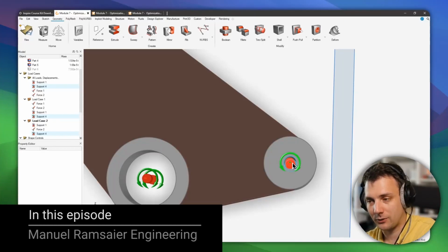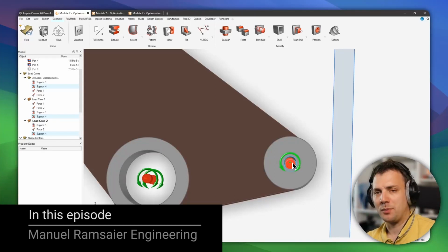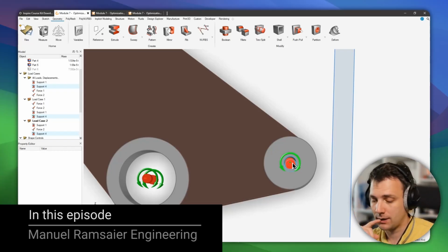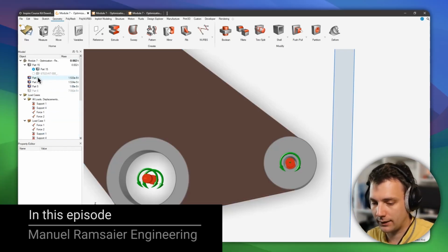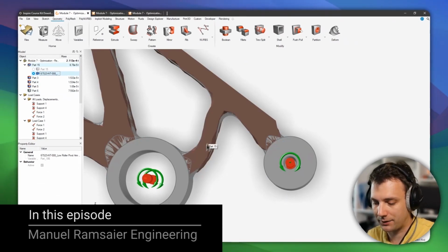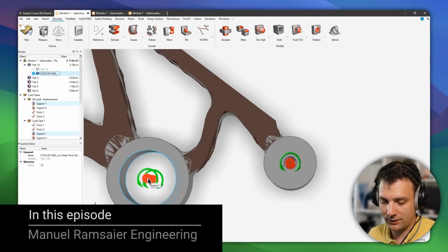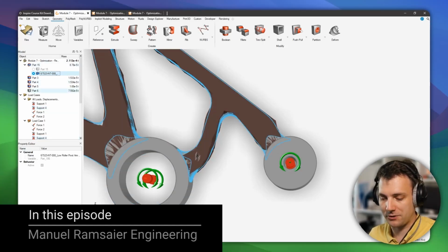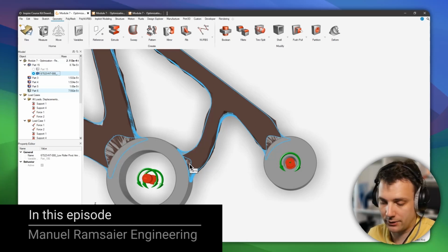But the point I'm trying to make is those two bearings right now, as they are set up, have infinite stiffness in the XY plane to each other. So they cannot move. And this is why structures like this can be perfectly fine and happen, because if you can make sure that this point does not move with respect to this point, then this structure is not really having any buckling issues, right?